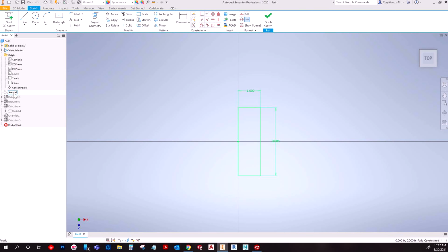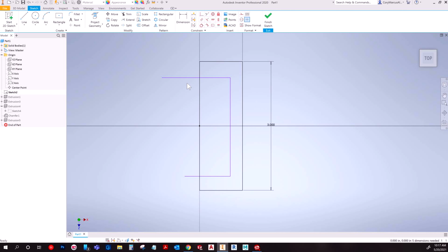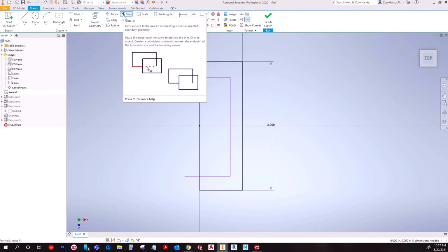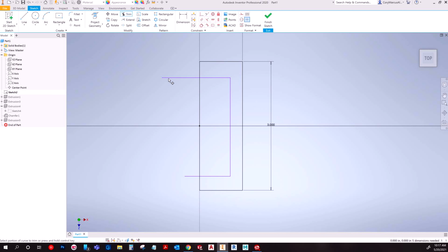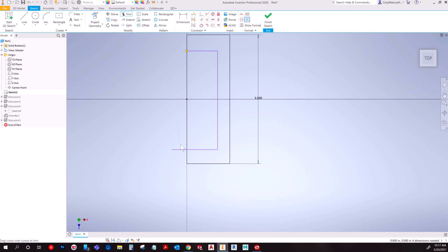That's pretty much it. There are some editing components up here. Say I decided for whatever reason I needed a little extra geometry in here. I can actually draw arbitrarily past an object, exaggerating, and you can just use trim. To give you a little look at it, you can click an edge and trim it. All I got to do is it'll recognize there's a boundary between this line and this line. I can just click and it'll trim it. I can also click, hold, and pull, and it'll trim multiple things. So I can go through here and just casually take a little tour of town and trim away.